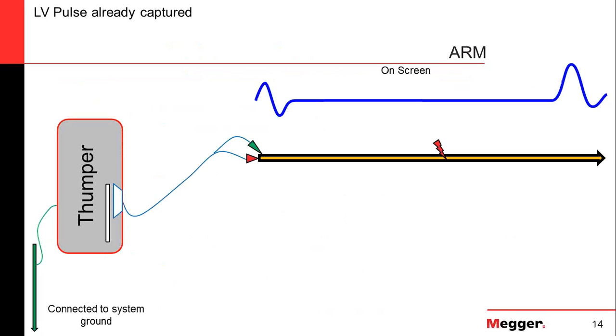So what this looks like is here we have a medium voltage cable, and you can see somewhere in this cable, this red lightning bolt represents broken insulation. There's a fault in this cable. Now when we just hook the radar up to it, in the low voltage mode, we see our characteristic hookup impedance on the left. We see this nice flat line, and right here where the fault is, we don't see anything because there's not enough impedance to reflect off of that fault. What we do see is the far end of the cable.